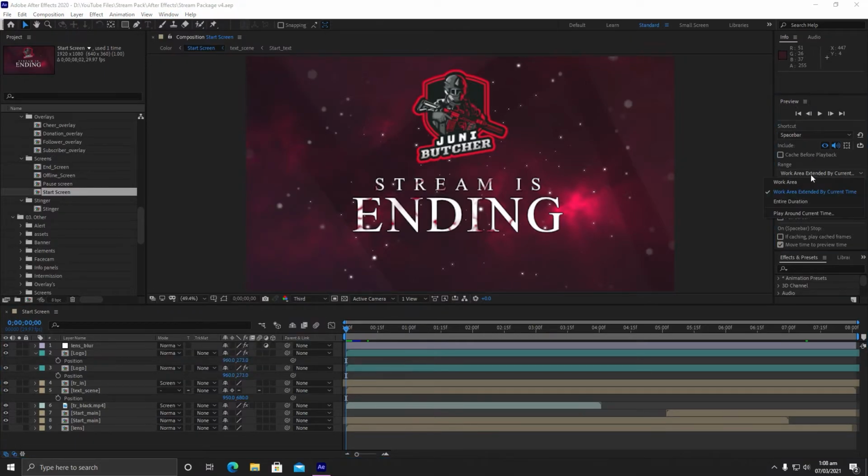Here you need to make sure it is work area extended by current time is selected, and resolution is auto, and skipping is 0, and frames are 29.97. Alright, and make sure this move the time to previous time is selected. So this is the first setting.